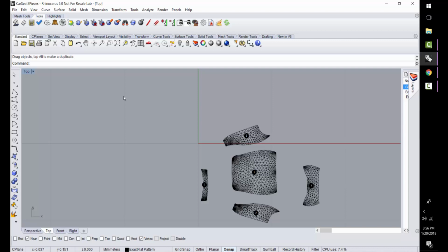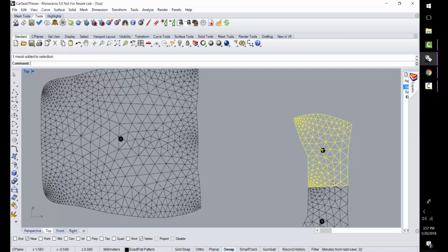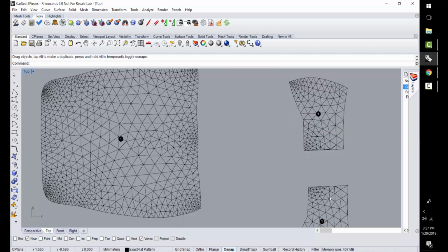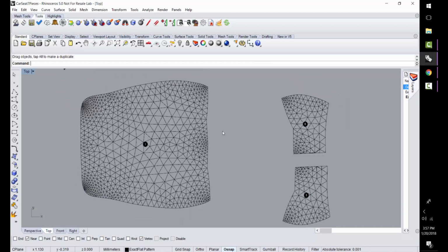Now, once we have this done, there's other things that we can do. For instance, if we wanted to make a cut in a piece, I can use several different cutters. We have a plane cutter, which allows us to select one edge and another edge and delete the piece like that. Again, as I've done that, it's added piece tag numbers. So I've cut using our plane cutter.